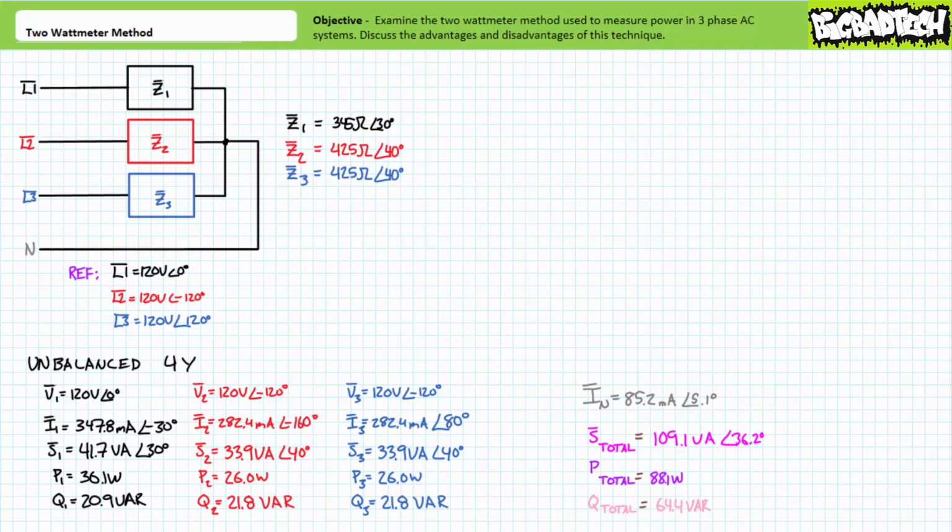For the unbalanced 4-wire Y configuration, each load impedance still directly experiences a smaller line-to-neutral voltage. Load current magnitude and relative phase shift for each load is proportional to an Ohm's law manipulation, as is power for each individual load. Given one of the loads is different, current and power for that branch is understandably different. In the unbalanced condition, current travels in the neutral line. Total apparent, total real, and total reactive power is the summation of individual apparent, individual real, and individual reactive power figures.